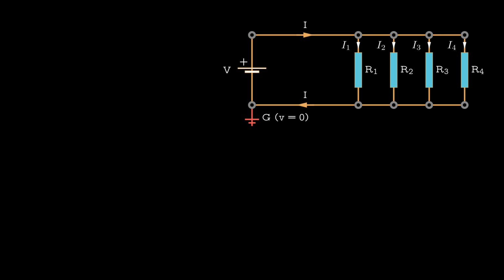The voltage along the conductor, connected to the ground, remains zero. On the other hand, the other end of the voltage source is at V volts, representing the voltage of the source. Since points A1, B1, C1, D1, and E1 form a single conductor with zero resistance, the voltage along this line remains constant, and equal to the source voltage V. When resistors are connected in parallel, the voltage across each resistor is the same as the source voltage V, but the total current is divided among the parallel branches.